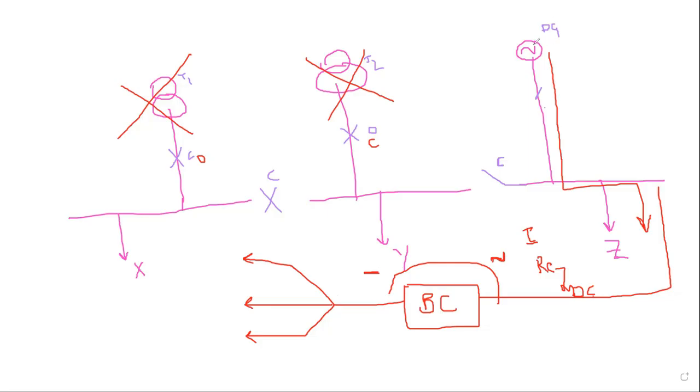Now, suppose the DG set has also failed, maybe because petrol or diesel was not available, or some other scenario. The relays still need supply continuously, because we have to provide a reliable supply to the relays. So in that case, I have one more setup, that is a battery bank.